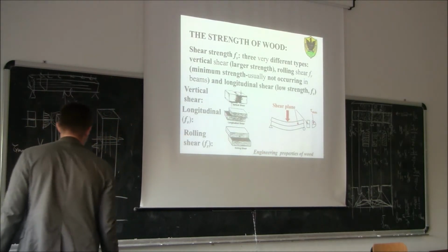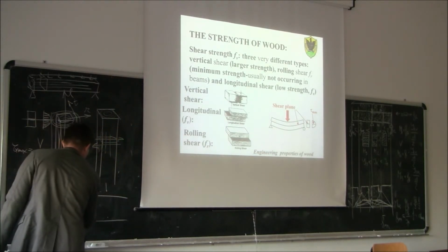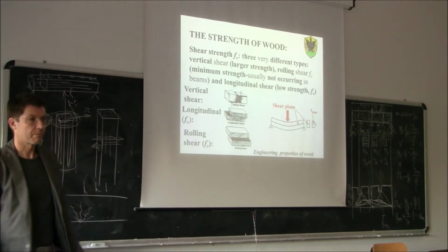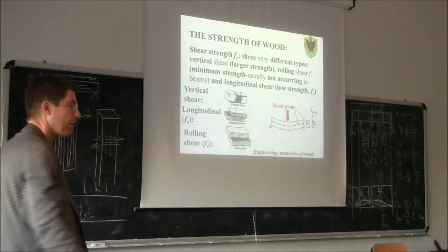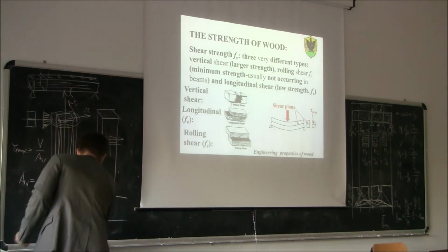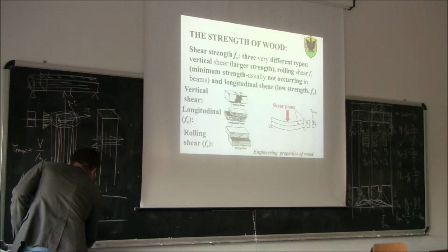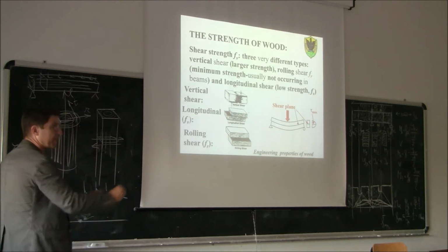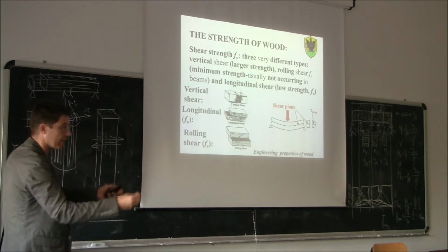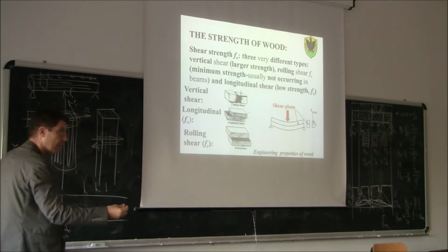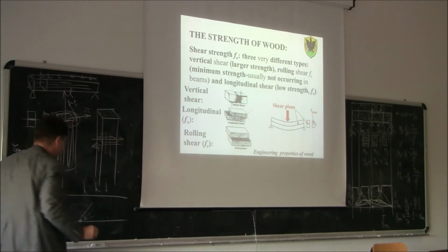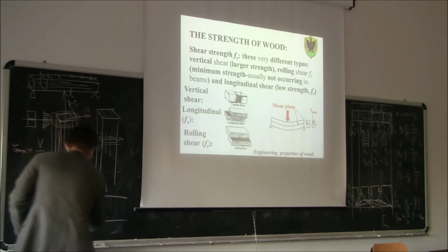How does it go? This way. So in the shear area, if you remember well, there is this failure mechanism, the Ritter-Mörsch truss. Basically, the crack is going to follow more or less 45 degrees.